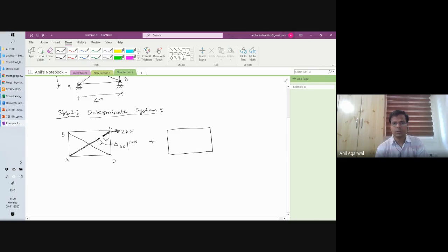So when I did this removal of this redundancy, I artificially changed the force in member AC to 0. So when I am applying this 2 kilonewton external load, this member AC is not carrying any load. It is basically moving away as if it is not a continuous member, but in reality, it is a continuous member. So what I have done artificially here is that delta AC, which was actually 0, I have made non-zero, and the force AC, which was actually non-zero, I have made 0.